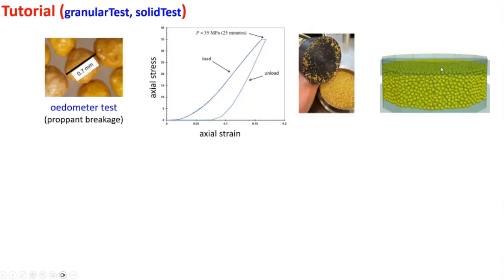What was going on is you can monitor the total force acting on the wall. We're going to give the wall a fixed velocity, which in our case can be interpreted as an axial strain, and the particles are going to push back. You can ask the wall at any time how much total force the particles are giving to you. By definition, if we take that force divided by the cross-sectional area of that wall, we can think of that as stress, right? So it's exactly mimicking a physical test.